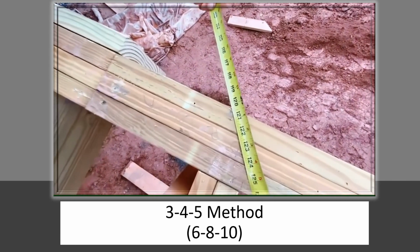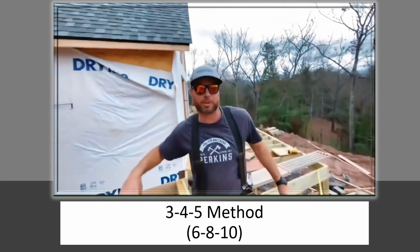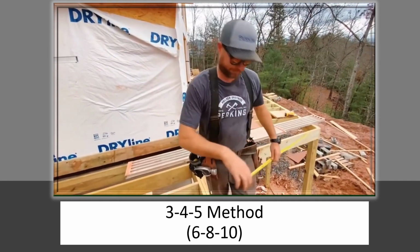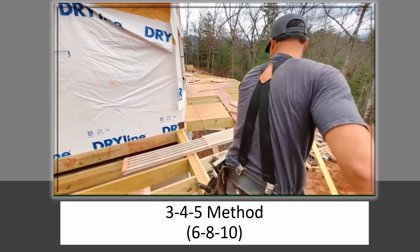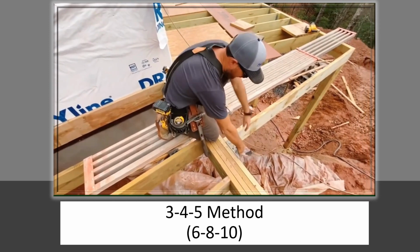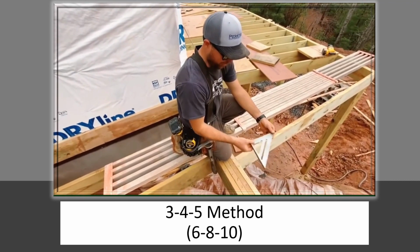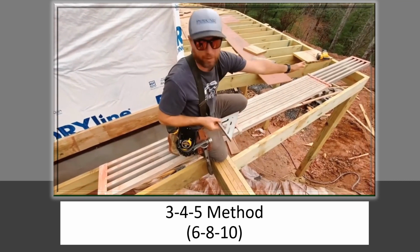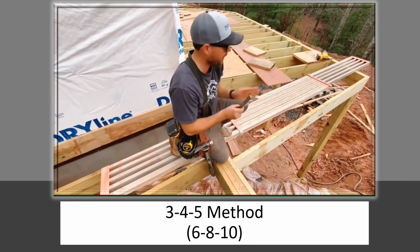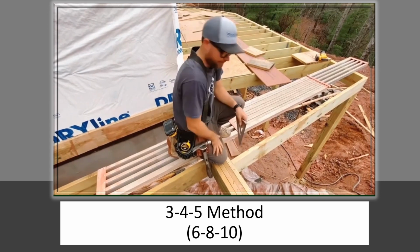All right, 10 feet and 3/8. So we're a little off. What I'm going to do is make some adjustments, and then we'll check it again. The reason I'm close to start with is because I used my speed square in this corner right here to get it close. But this is a short length right here, so even if it looks close, when you go that far out, it could be way off. So that's why I'm checking this bigger triangle to make sure that this actually is 90 degrees coming in.